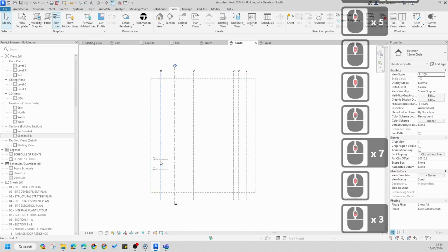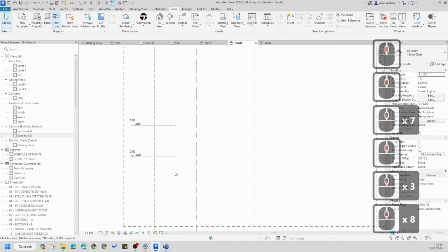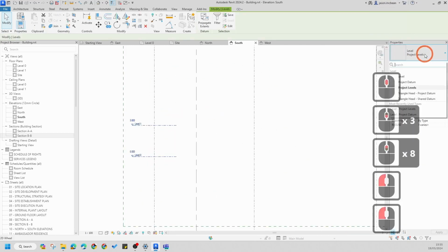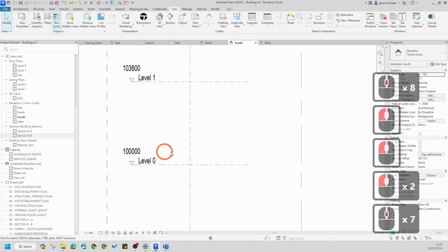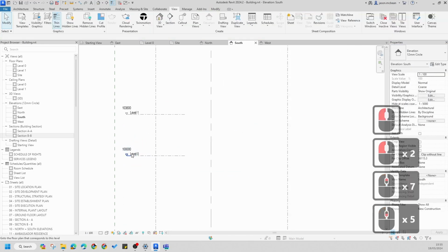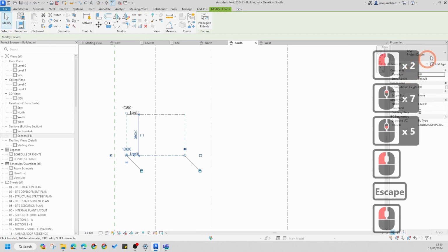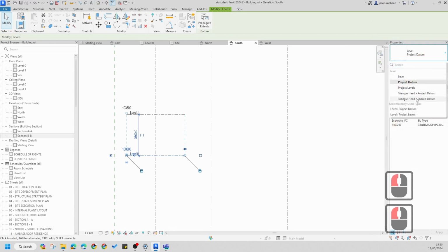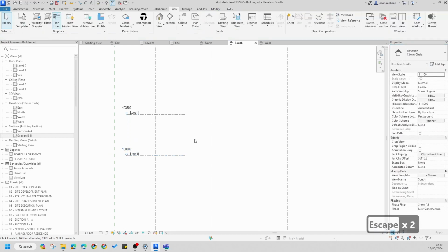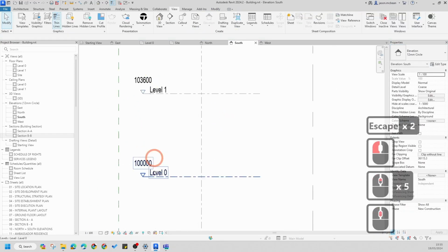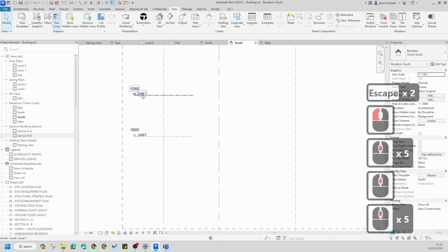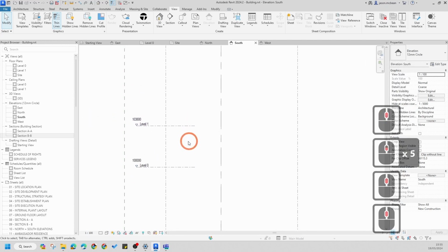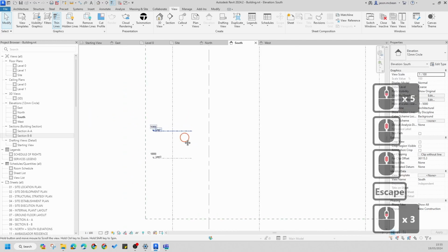Now what I'm going to do is make a series of levels, and I'm going to change this level to datum. So I'm going to change this to project datum, because we're going to use a datum for this project, but at any point in the project you can go back and change these back, and we'll use some other levels later on. I'll explain how we use above sea level, but for the rest of this year, just to understand, we're going to adopt this datum approach, based on the information that RB is giving you.